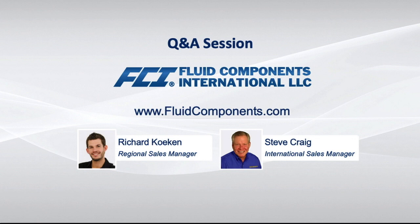The additional consideration is the field optimization possibilities. So in the event that there is a field optimization possible, fewer measuring points can be selected and then corrected in the field on site. Typically, it depends on the manufacturer how many measuring points can be used on one measuring system. For example, at Fluid Components, we have a solution up to 8 measuring points connected to a single remote transmitter. So that's plenty of measuring points for a very, very large diameter.